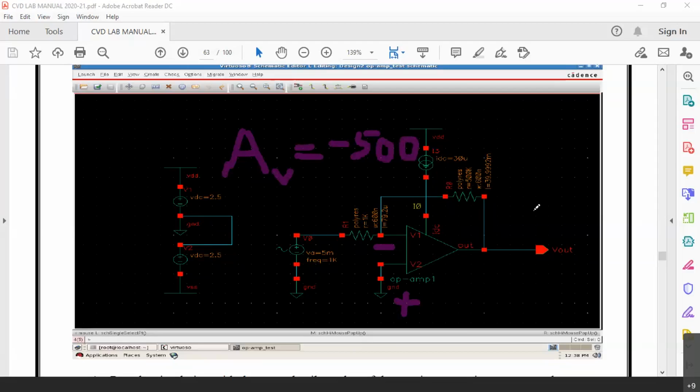As I mentioned earlier, when we need a resistor, we have to use those layers, either polysilicon or NWell, which have enough resistance. As the polysilicon layer has resistivity, we can use it as a resistor here, because finally we have to make a layout inside the chip. It is not like a discrete resistor. Now this is an integrated resistor.